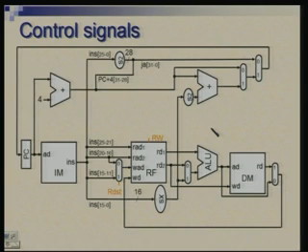Then the register file needs a control signal to tell it whether it has to write or not. All instructions, you would notice, are not writing into the register file. It is only the first 5 instructions and the load instruction. These 6 instructions out of the 9 write into the register file. So this will have to be made 0 or 1 accordingly.